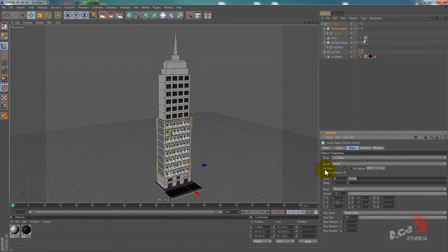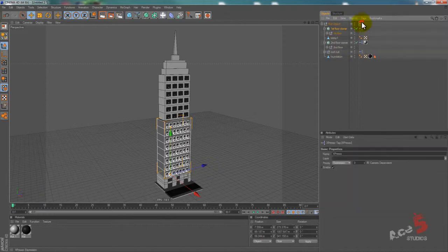Just in case, one more time I'll go over it. Right now we were calculating these correctly, but we were calculating this Xpresso tag first. And this Xpresso tag had the roof, so it was like, where is the roof going to be? And it looks through where everything is, and then it places the roof in that position. And then it goes and sees where the first floor and the second floor are, but their position changes. So the roof position only updates the next time you update.